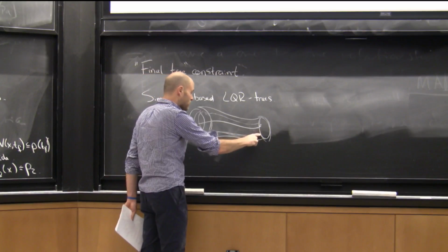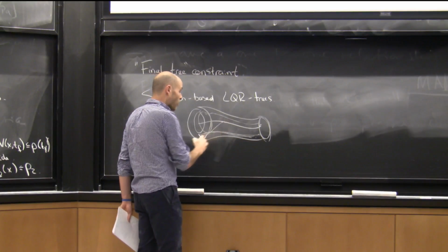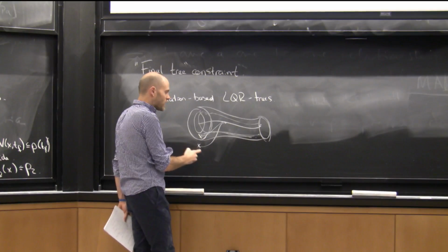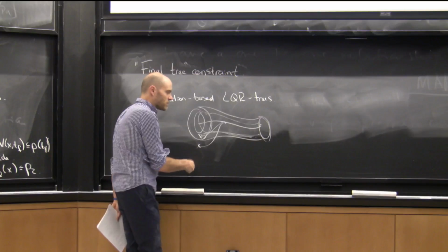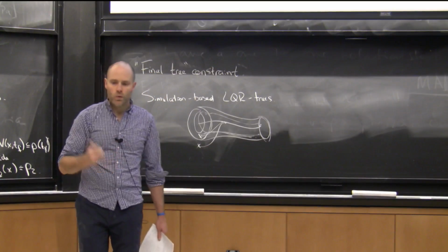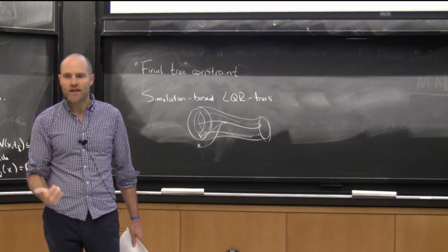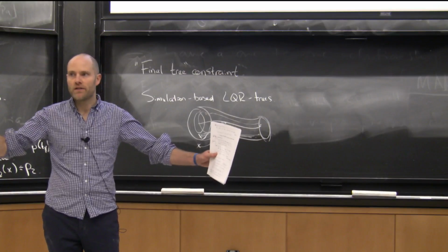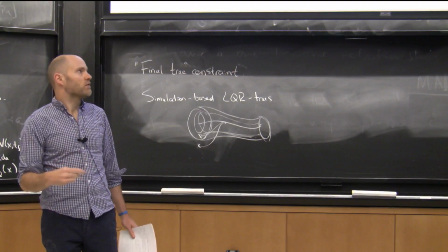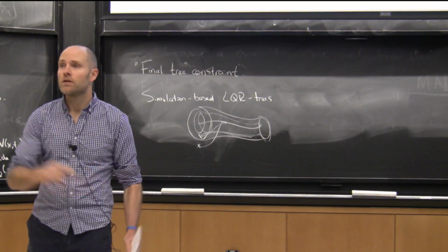I'll execute that controller. If it failed, now I'll add trajectories to the library, or if it ended up in free space, I'll add trajectories to the library. So it has a lot of the same space-filling properties, but you don't have to worry about sums of squares. And at the time, we did that because we weren't sure how to handle inequality constraints like input saturations and the rails on the cart pole nicely in sums of squares, but that's all been resolved. We could have handled that problem completely with the sums of squares formulation now.